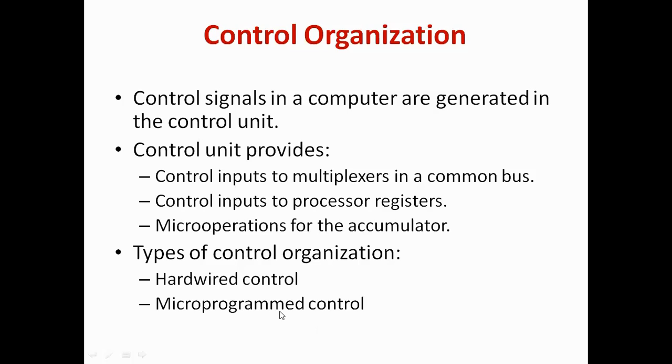And obviously, this will be slower than the hardwired control, because we have to run a program for every control signal, but it will be flexible. If we want to make certain changes in the control signals, or put new control signals there, we just have to update the program in the control memory.